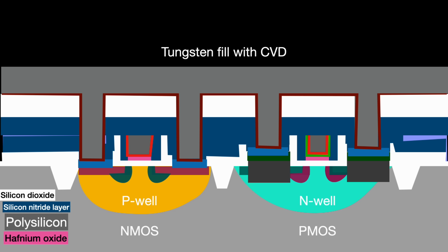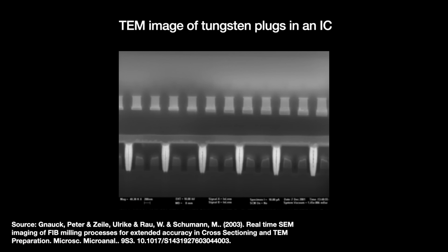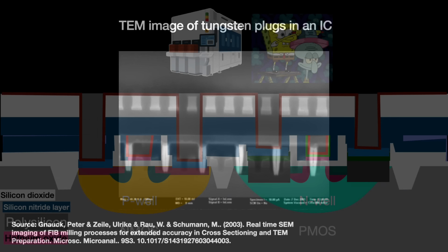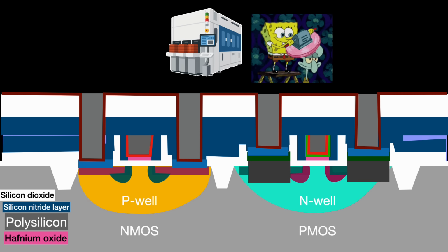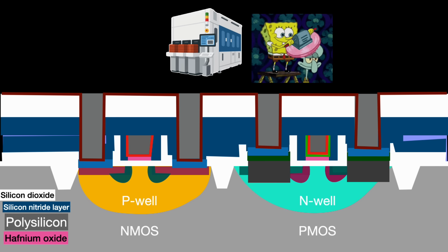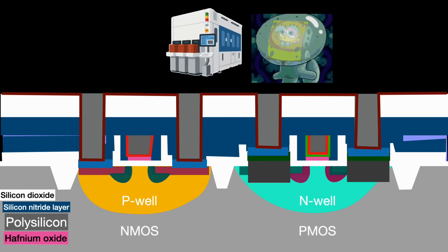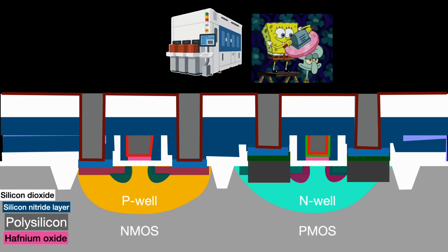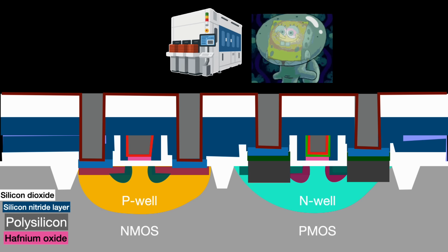Progress on the tungsten films is measured using the aforementioned spectroscopy ellipsometry, but the only way to look into the plugs themselves is with an electron microscope, which means it has to happen off the line. Anyway, once the tungsten is applied, we use CMP to polish it all the way back down to the silicon dioxide ILD layer. Progress is good. The plugs and contacts are done, and we are now ready for the first interconnect metal layer.